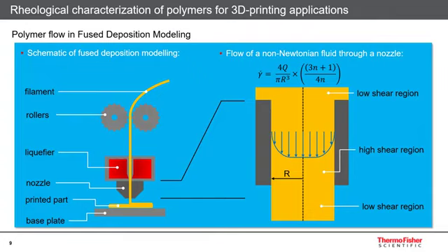If the viscosity is too low, on the other hand, the material will flow way too fast through the nozzle and no precise dosing is possible anymore. The correct viscosity of the sample at a given shear condition is usually adjusted by nozzle temperature. Rheological measurements can be used to measure the shear rate depending viscosity of a polymer at different shear rates.